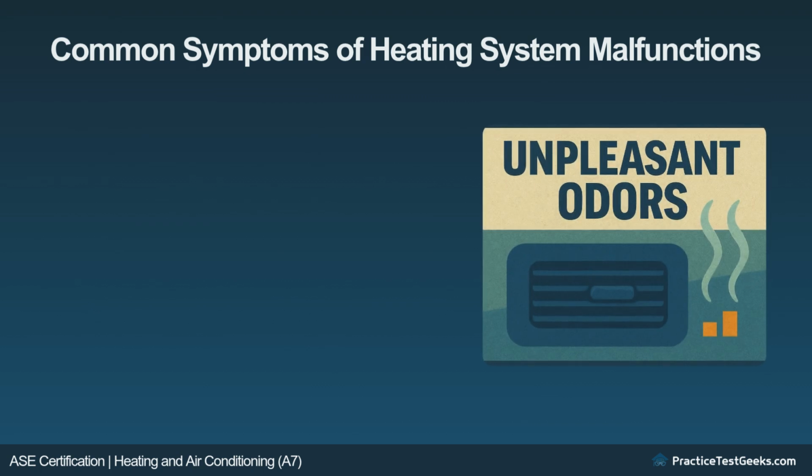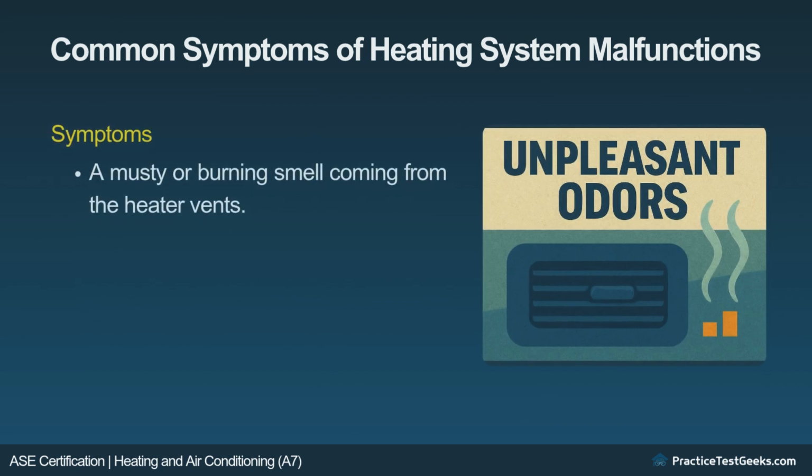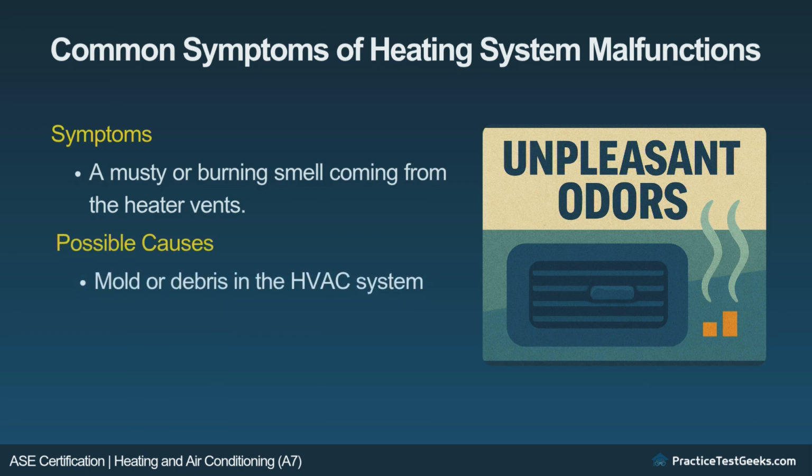Unpleasant odors. Symptoms. A musty or burning smell coming from the heater vents. Possible causes. Mold or debris in the HVAC system. Moisture inside the heater core or ducts can cause mold or mildew growth. Overheating coolant. Overheating coolant can emit a burnt smell when it enters the cabin through the heater vents.